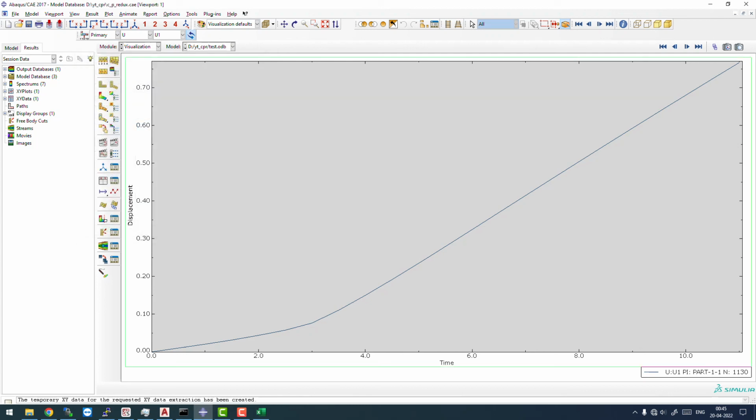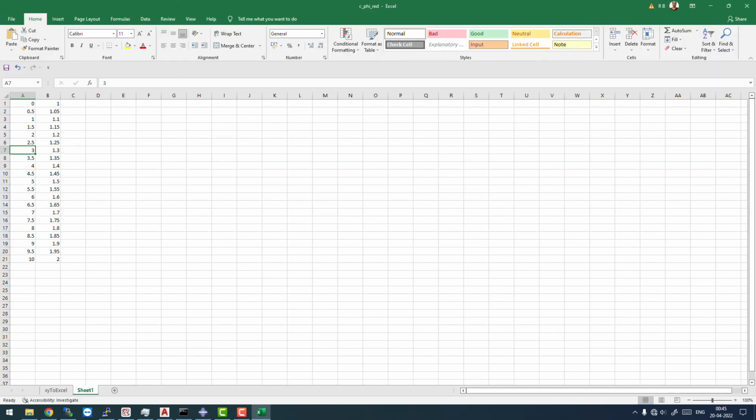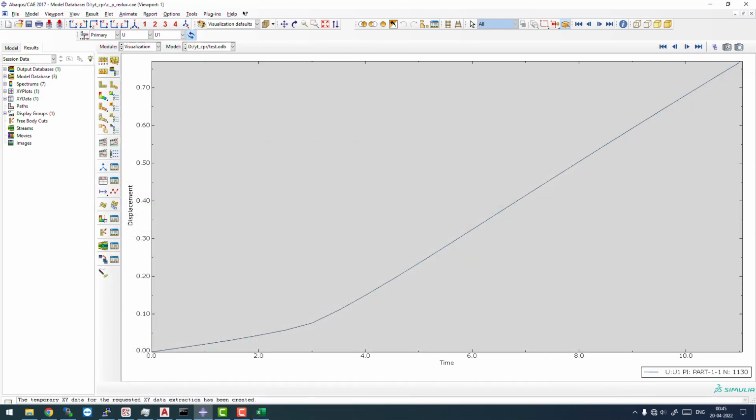Basically, the point where the displacement starts to rise drastically, or your analysis basically fails, is the location where you have actually found the factor of safety. So in this case at the time value of 0.3 the displacements are starting to rise drastically. You can see the angle has changed very drastically here, and at the time value of 0.3 the reduction factor is 1.3. So that's what I mean by 1.3 reduction factor, which is the actual factor of safety which we found for this specific slope.